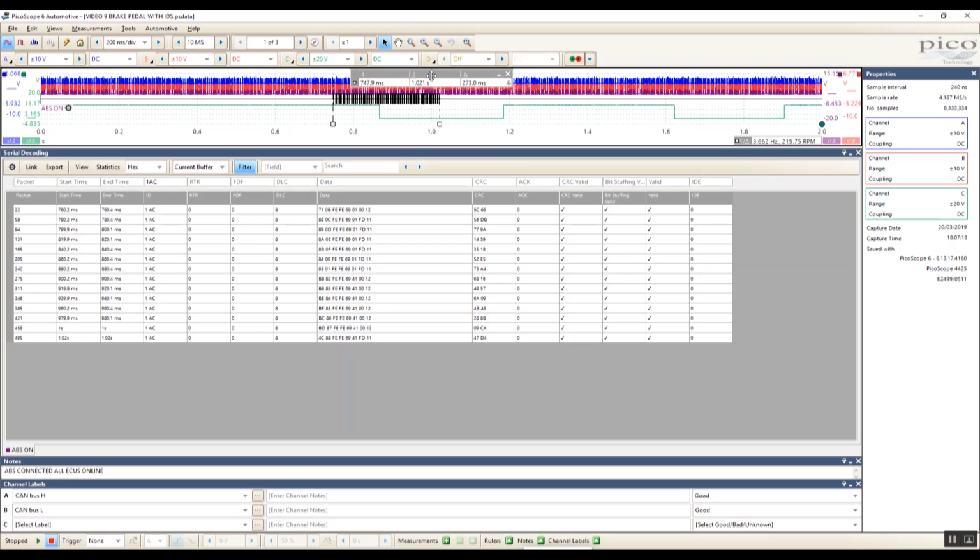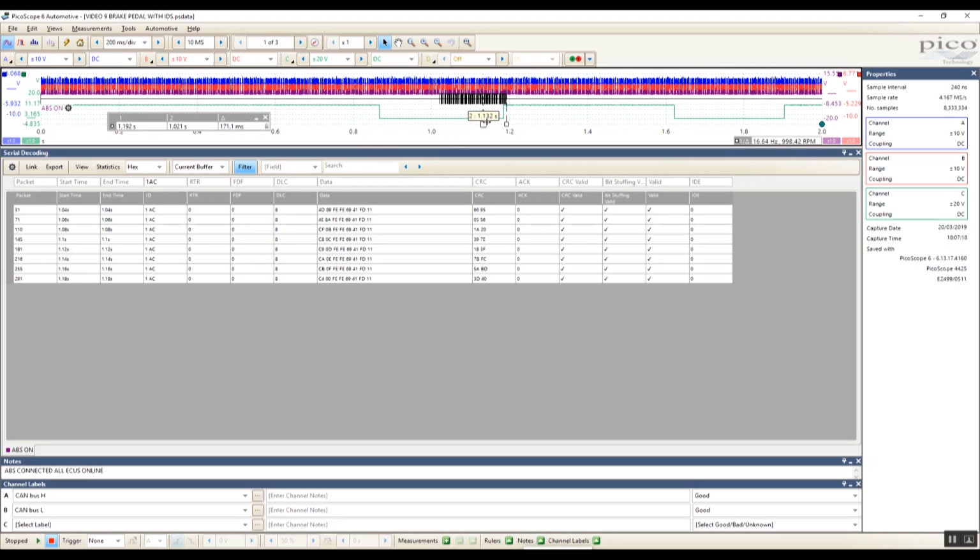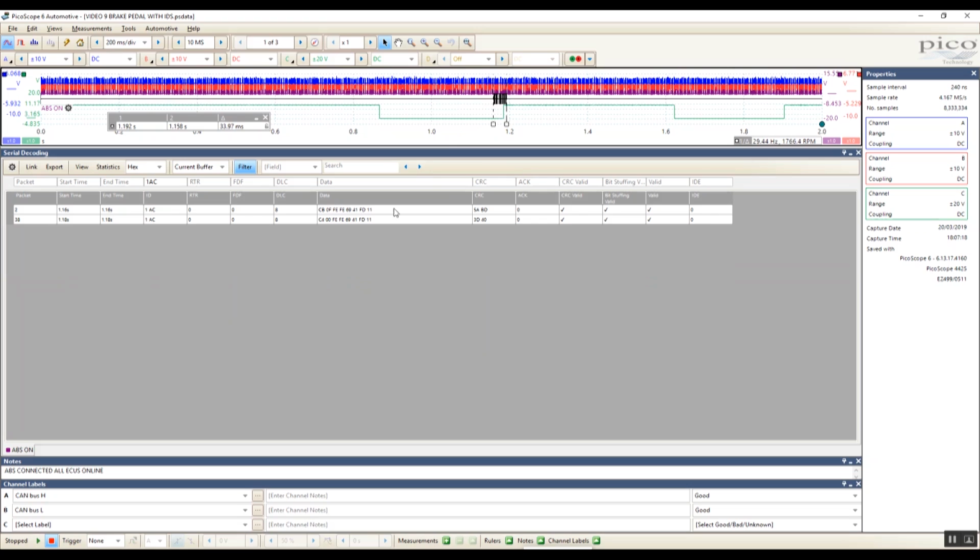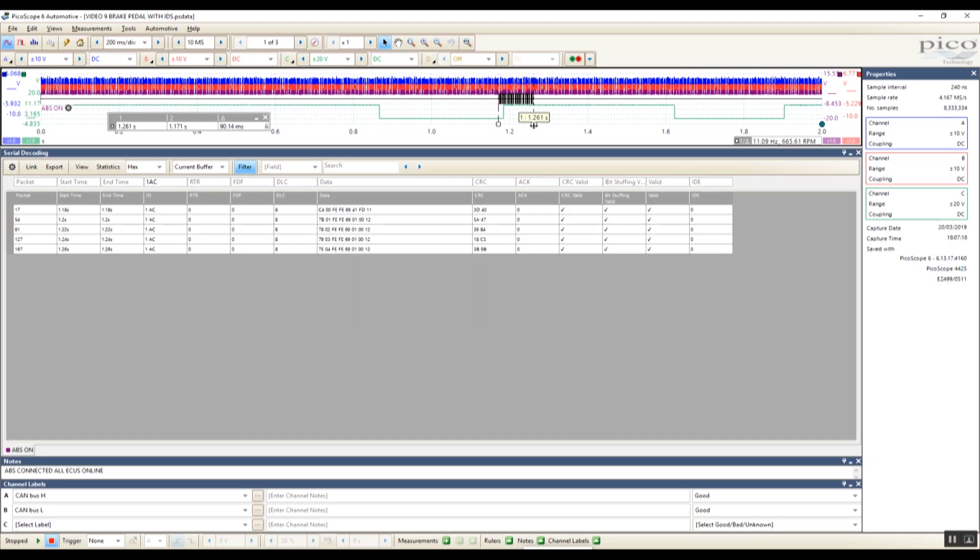So again, that is looking like ABS ECU, because we know this ID is missing when we disconnect the ABS ECU. And also now we can promote a response in the payload when we press the brake pedal. And again, let's just see how fast this responds. If we decode right over here into this area, we are at 4101. 41. Yeah, so 01 is brake pedal off.